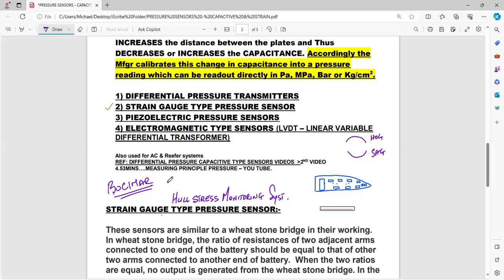Okay, normally you also load iron ore in Brazil. There is one particular port, I forget the name of that port, where, with lightning speed, they load your ship. And our particular fleet of bulk carriers at P&O had this hull stress monitoring system, and therefore there was no incident. The moment that hull stress monitoring system gave an alarm, the chief officer would stop the loading and tell them to shift to another hatch.